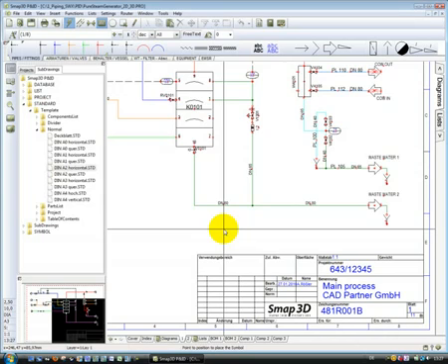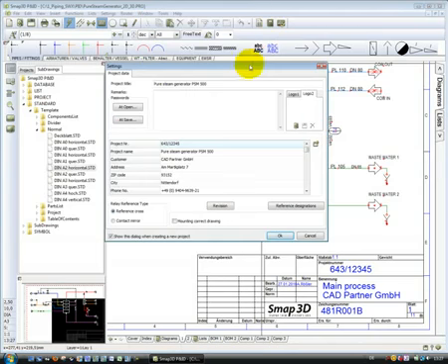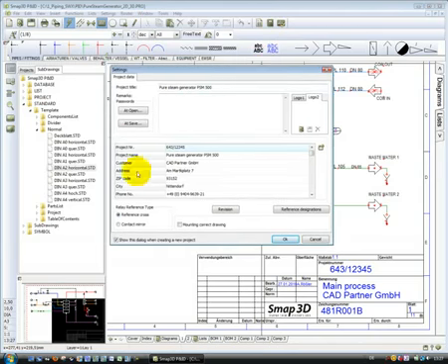For the filling of the information, it is not necessary to type some text in such a drawing header. No, this information is coming from some property sheets. Here we differ between the project data and the sheet data or the page data. The project data is, for example, a mask that can be prepared with the required information and properties which are valid for the whole project. That means every field you see here listed in the left part of this mask, it is possible to add, edit or remove from this list. Every company can prepare the templates with the property content they like to work with.